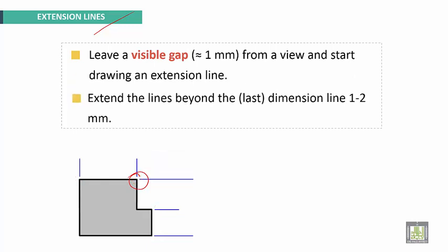Extend the lines beyond the last dimension line 1 to 2 millimeters. Extend the line here and here 1 to 2 millimeters. Here also, this small extension.